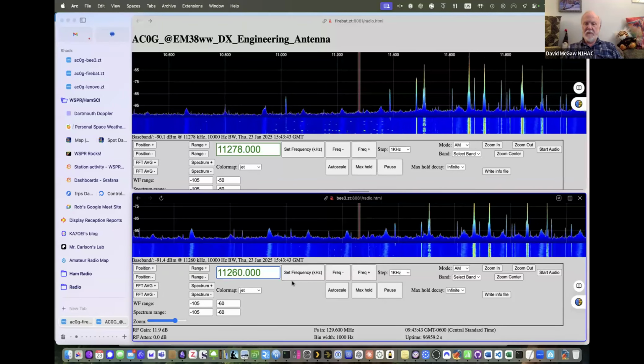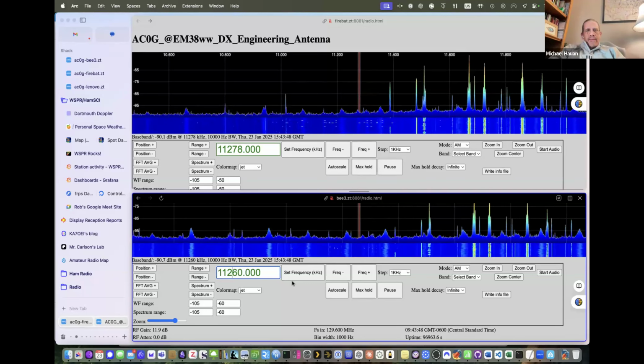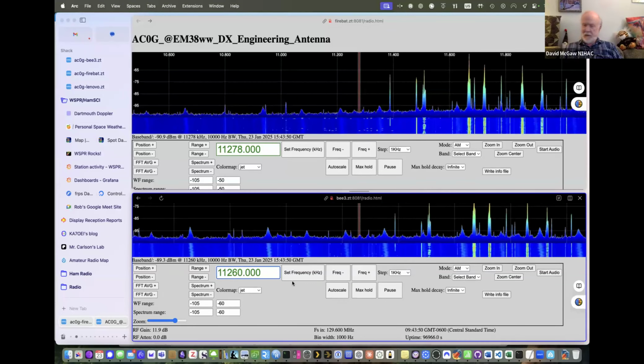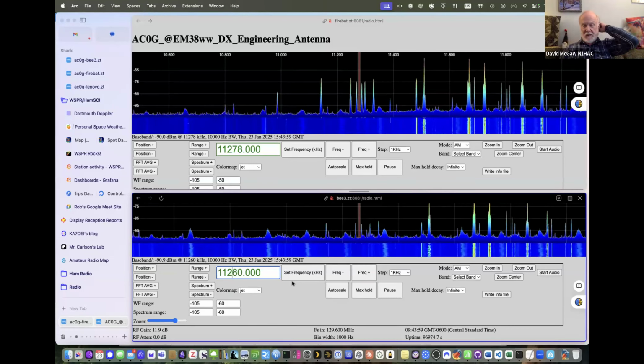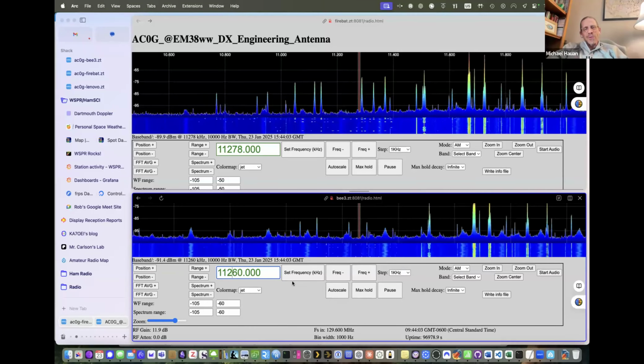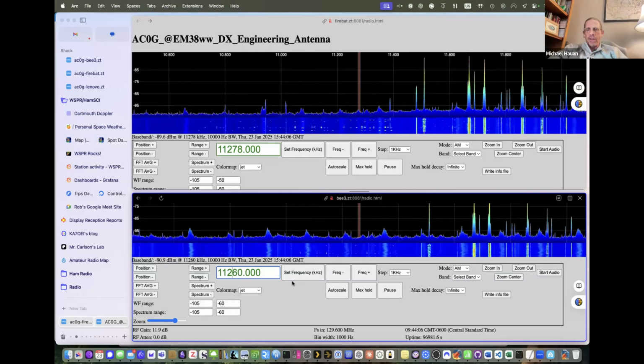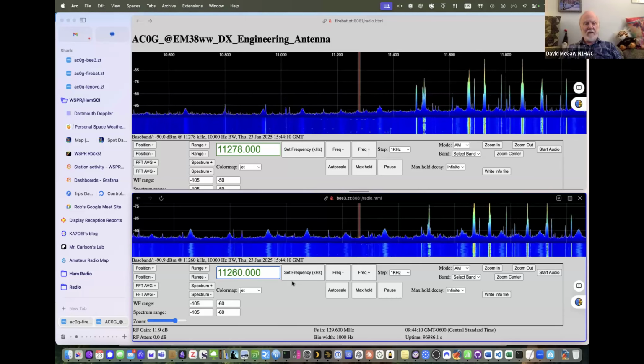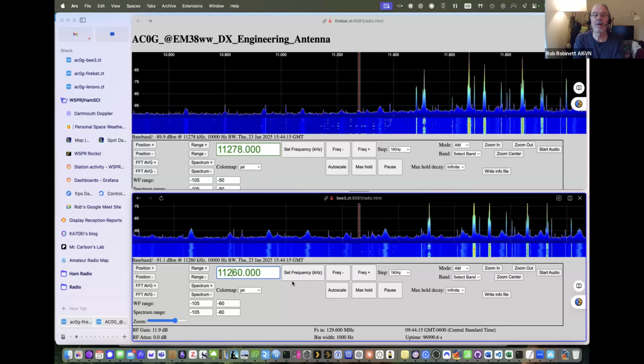Michael, do you have any 140 or 240 toroids? Because if you just wrap a bunch of 316 or 174 around that, pretty much of any mix, but like a 43 or a 61. As part of my efforts, I just ordered several of those from Palomar Engineering, and so I'm going to start wrapping some stuff up and see what effect it has. Yeah, because we use those all the time.